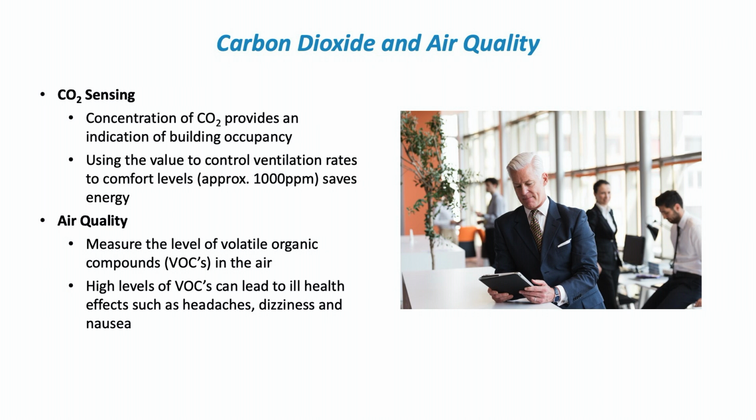That varies depending on the application. You probably could get away with 1,500, although people will start yawning. If you're doing schools, then people are asking now for 750 parts per million. So there's more fresh air and less CO2. But 1,000 parts per million is a fairly established center point for this.